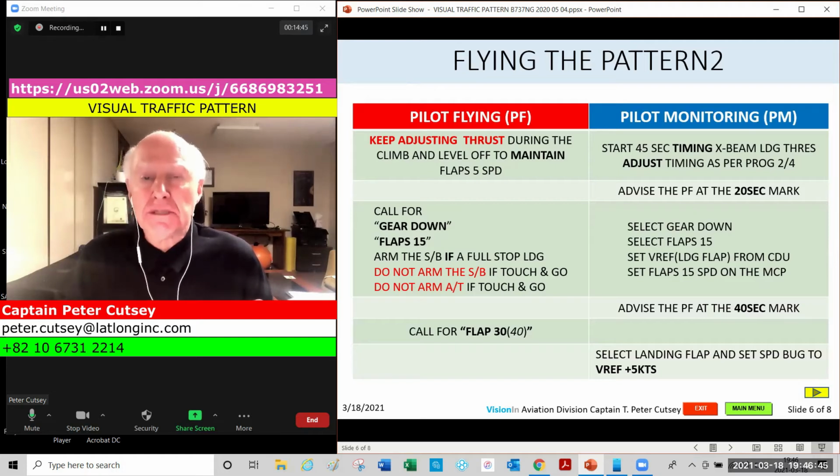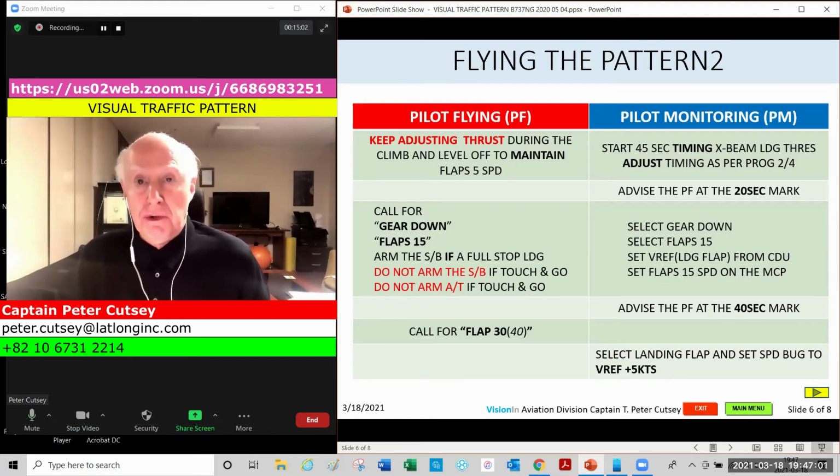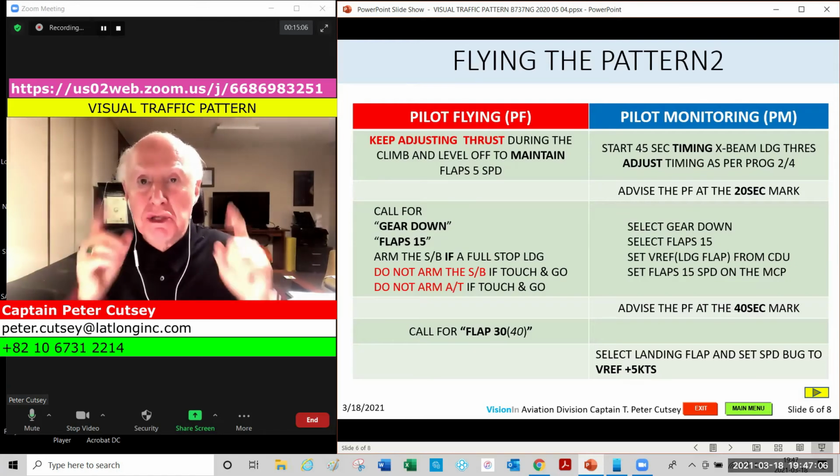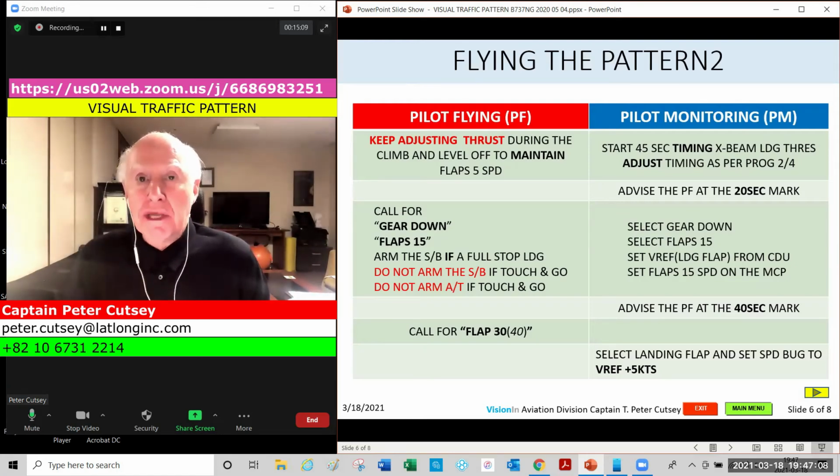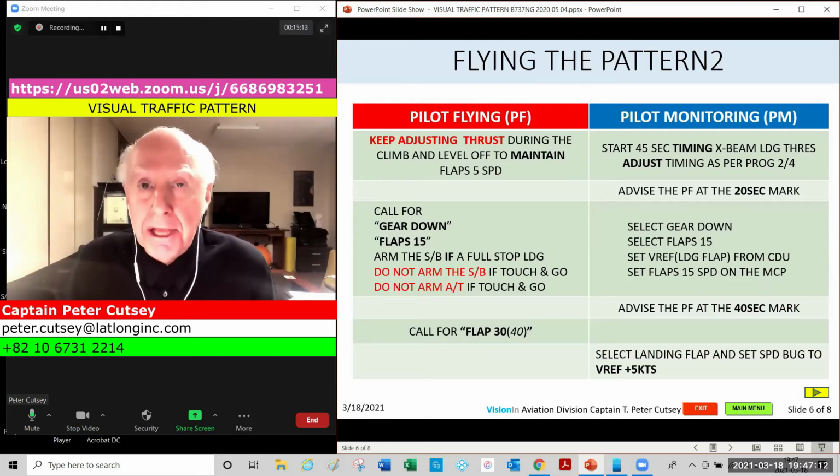I really suggest, because you're close to the ground, that you don't pull out checklists. This is one particular case where you're going to brief on what you have to do for the after takeoff procedure, and then the landing checklist, which is basically very simple. You follow what your instructor tells you, but when you're close to the ground, your eyes and brain should be outside and not looking inside at checklists. In any case, your instructor will tell you what to do.